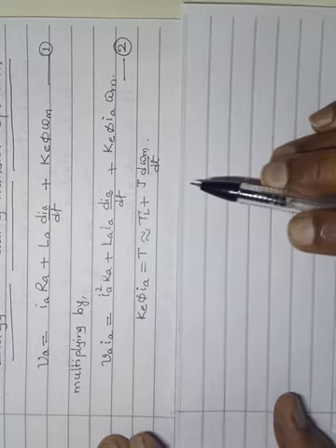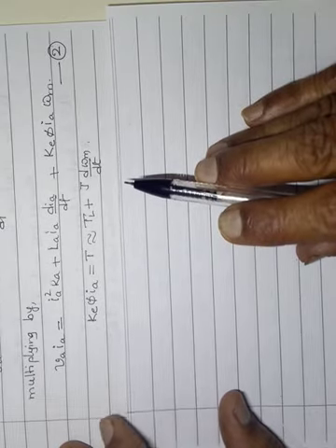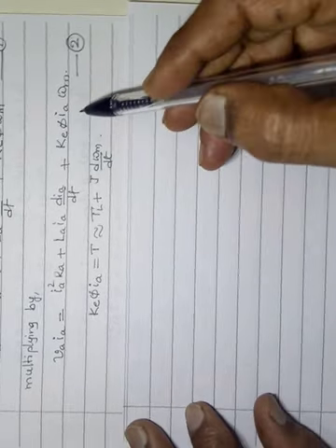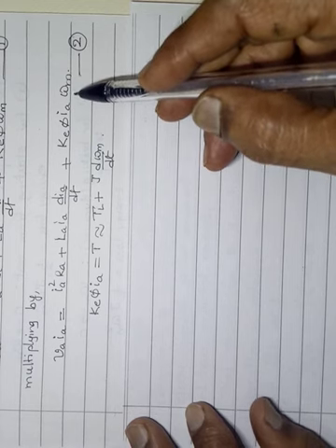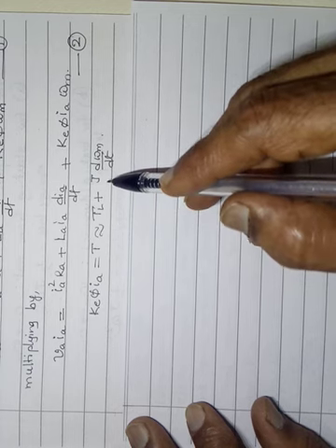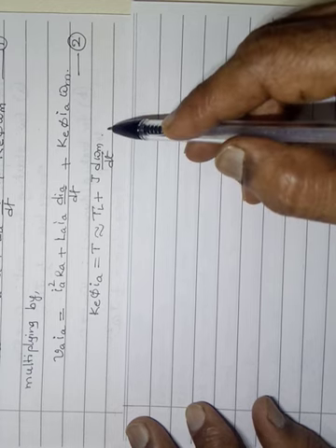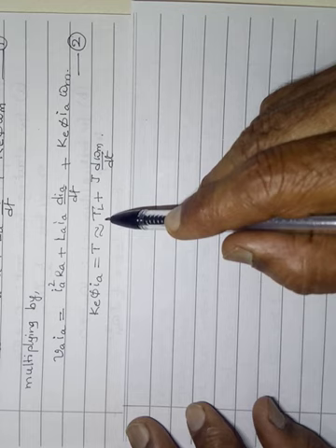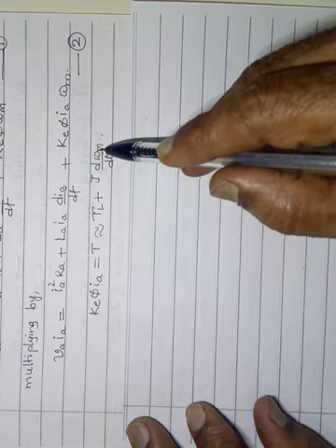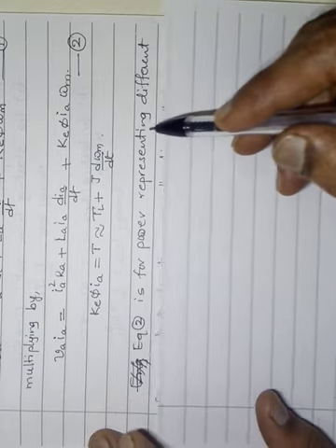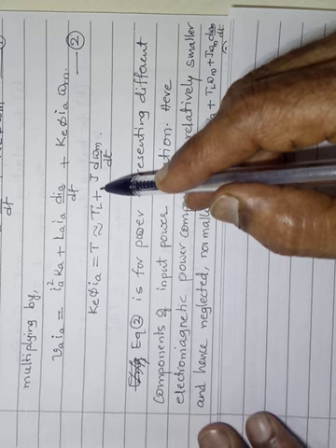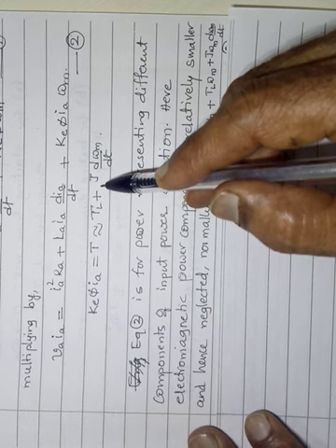So in equation 2, in this Ke pi Ia, we already know that it is T, the torque. The torque had 3 terms. Approximately it can be put as TL plus J d omega m by dt, because normally that third component is lesser in magnitude.